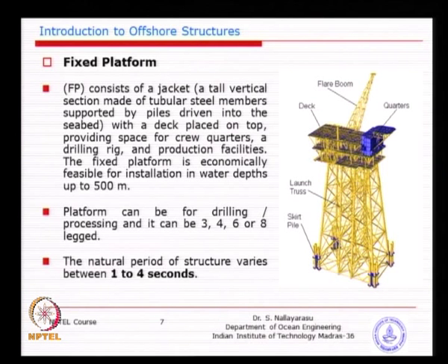But if you take a similar system and go to a floating system, you will see that the periods could be as large as 20 seconds, 30 seconds, 40 seconds. So, you either have it there or here, you do not come into a lock-in period of 4 to 16 seconds. It is very good, is it not? So, that is the idea behind it. We will see in the last slide how people have designed over the last 30-40 years, either below 4 seconds or beyond 20 seconds, which is away from the wave periods.